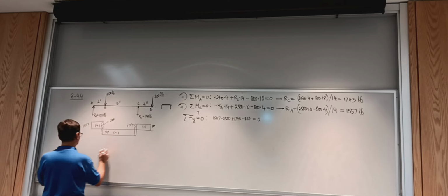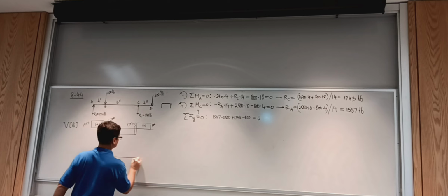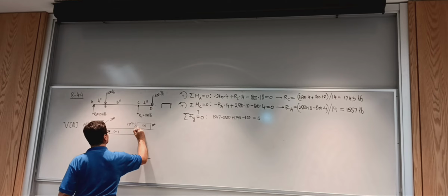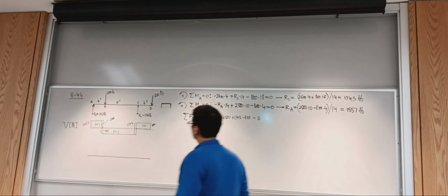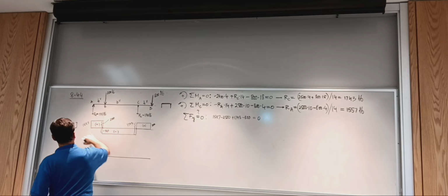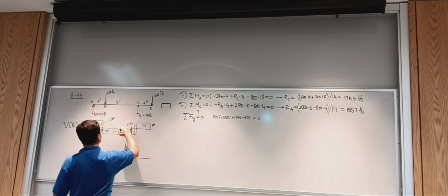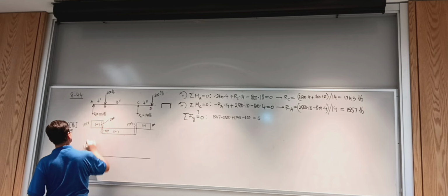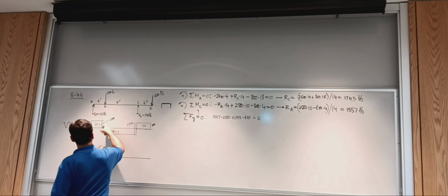Then I have the moment diagram, and you're expecting two cusps. So the moment diagram starts with the maximum slope. I look at the value. So these are slopes. Actually, no, this is the max. No, I'm sorry. This one is the maximum slope. And it's positive. So a moment diagram moves up, and then this is where a maximum happens.